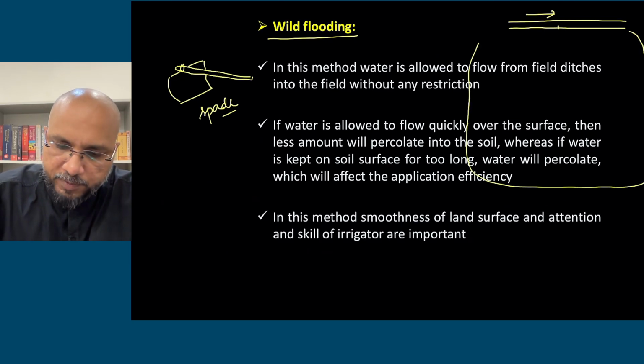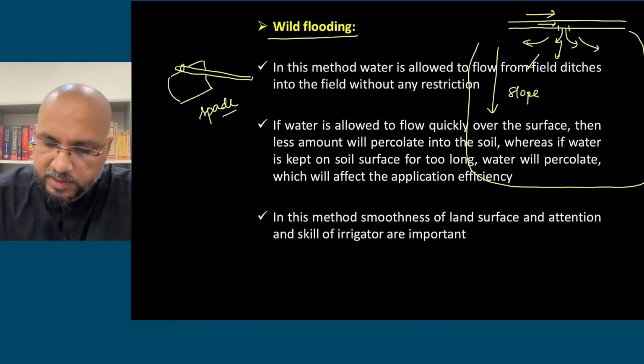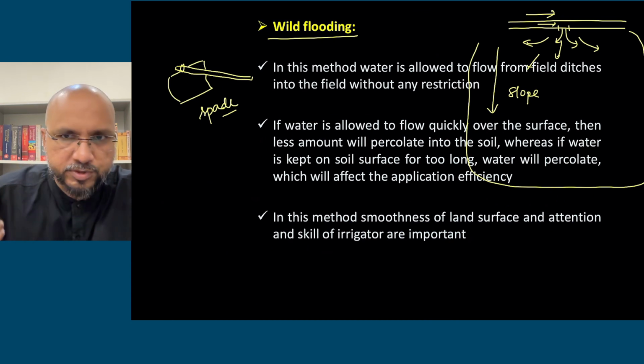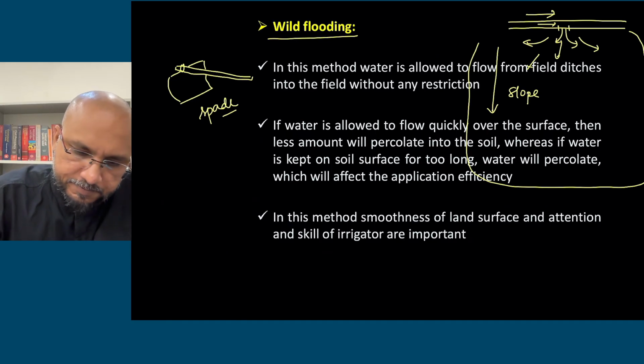So he will open the bund, water flowing in the ditch will enter into the field and there should be slope in this direction, तभी तुम्हारा water distribute होगा. Okay, so from higher end to lower end, from upstream to downstream, water will flow in your field.